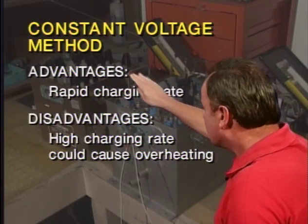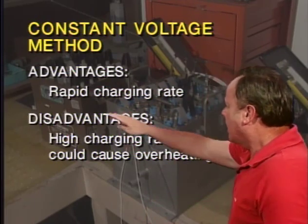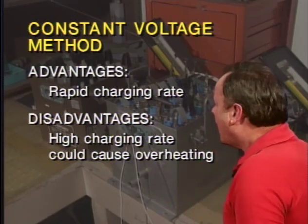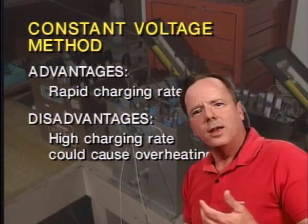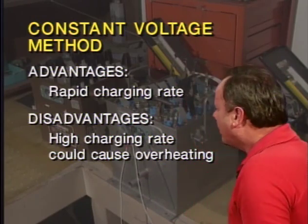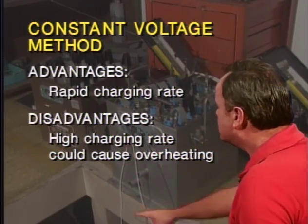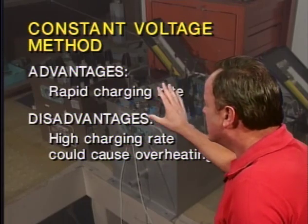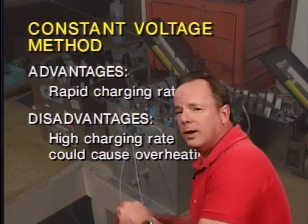Now the advantage of the constant voltage method is that you get a very rapid charging rate, particularly when the battery is very discharged. However, the disadvantage is if you have a NiCad battery, that very high charging rate could actually cause the battery to overheat. So that's both the advantage and disadvantage of the constant voltage method because you're not really controlling the rate that